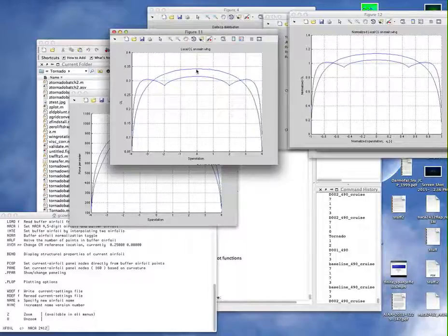So really what you'd have to do is use Xfoil to integrate this entire distribution. You have differing Reynolds numbers, differing lift coefficients, different chords, etc. So getting at the actual friction is tricky. Xfoil could do it in sections, what they call strip theory, or you could run a real 3D code, which would also include the span-wise velocity field, which is particularly pronounced on a swept wing, unlike this case. But we're going to do a simple way, exactly as I outlined in the project.